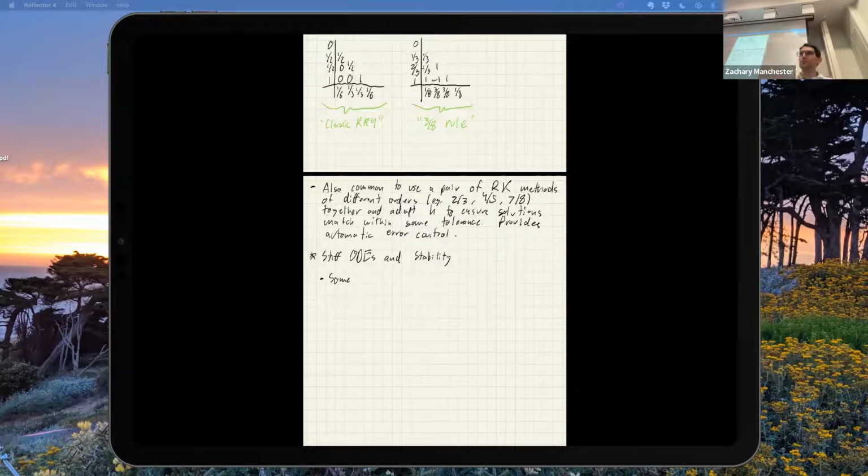By the way, this stiff thing happens all the time, especially in robotics. If you're doing impedance control with high gains, that'll make it stiff. If you're trying to simulate contact interactions with some kind of spring-damper model, that makes it stiff. This happens a lot. It's not a rare thing by any means. It's very easy to end up in these situations.